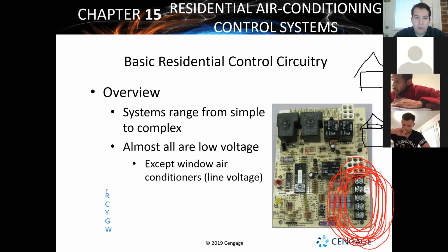And you're just going to have to know that R needs to be 24 volt power, C needs to be your common, Y is your cooling call, G is your fan, W is your heating. You learn those connections, and you memorize those. You can learn to troubleshoot and figure out a system very quickly, very easily, save yourself time, and also make it so that the system can keep coming back on faster, but save yourself time, get yourself more money, save the customer time, save the customer money. You know, it's always good to do that kind of stuff.